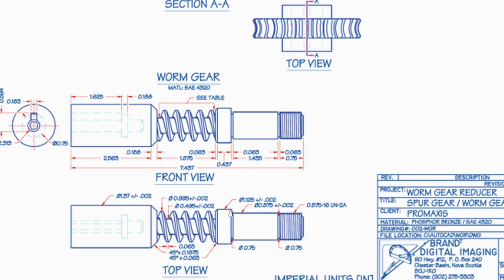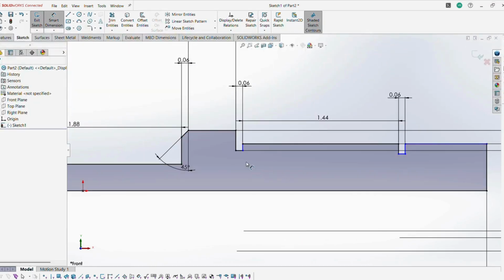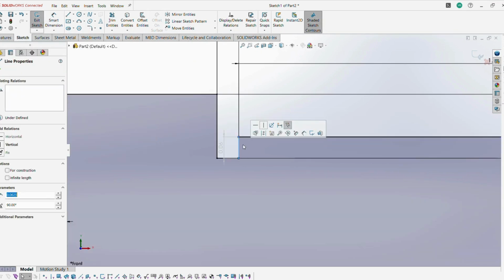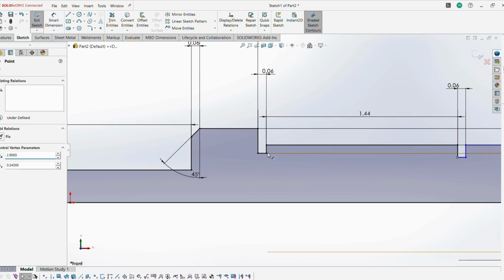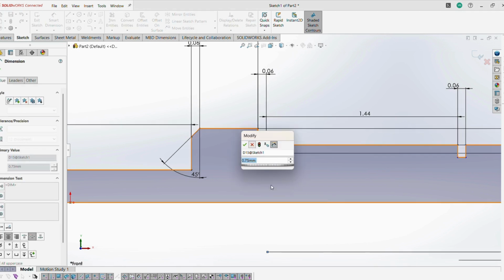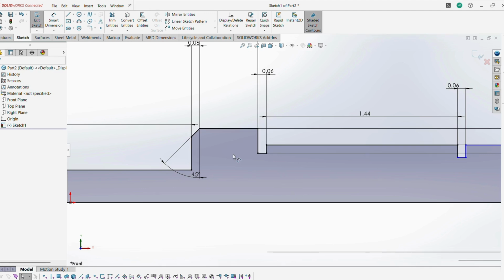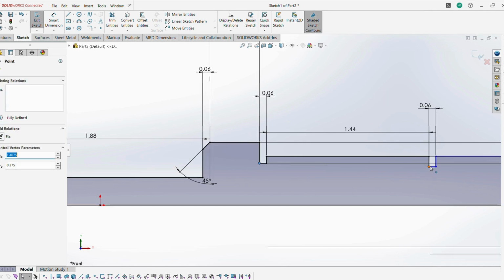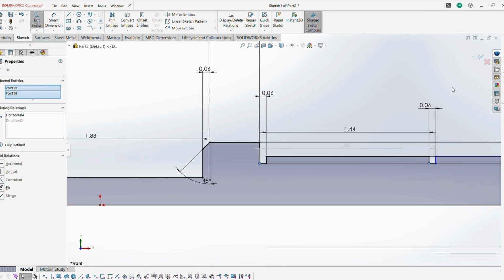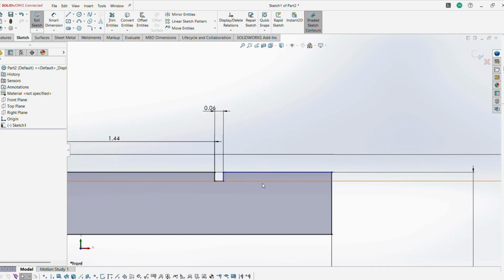The same as the other kinds of dimensions. Choose this vertical line, select this endpoint as well as the other endpoint. Instead of that, I just randomly select the dimensions. Choose this endpoint first. Select both endpoints, one fixed and one movable. Then use a horizontal constraint to fix it linearly.